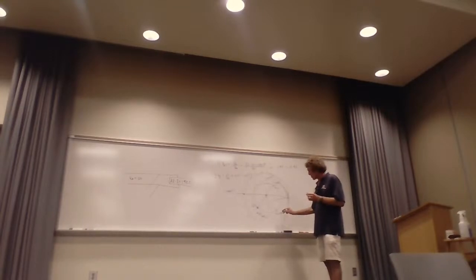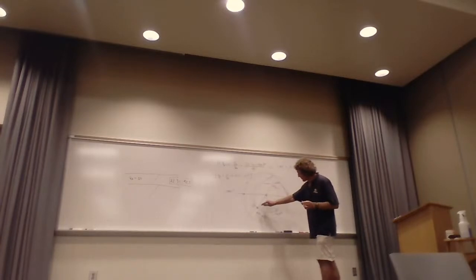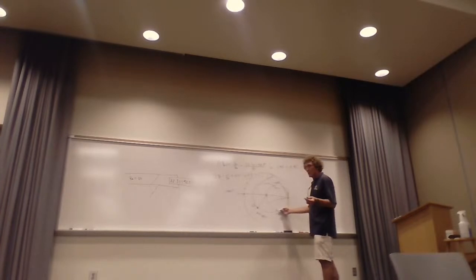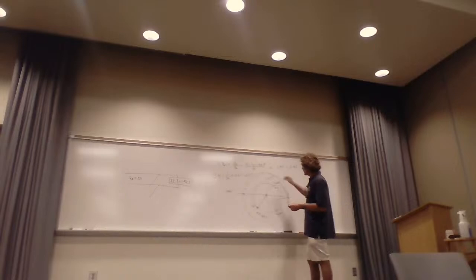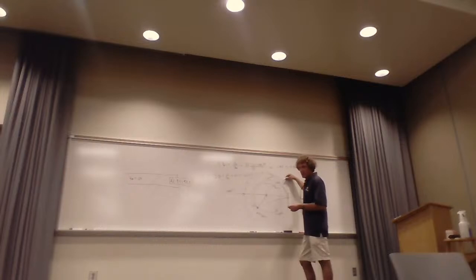That's one solution. Or we can move from the load, from the antenna, to this point, which would be 1 minus j0.8. And then because we're going to add something to it, we'd land at the 1, and we'd want to be at plus j0.8. Does this make sense to you? Now, I'm not sure which one he took.